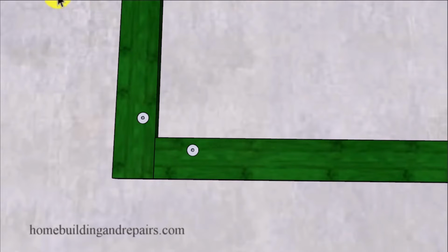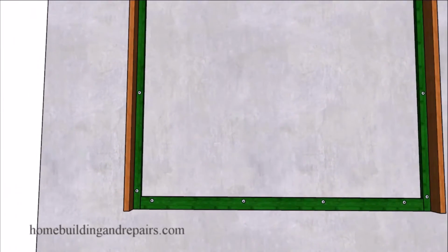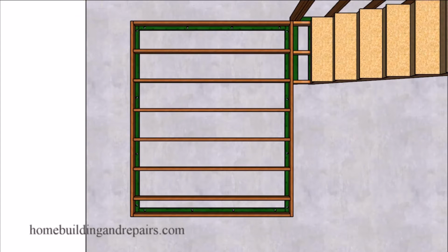And to give you a better idea of what I'm talking about, let's go ahead and install the rim joist on each side. And if for whatever reason you need to notch any of the framing components for the floor joist or the rim joist here, that's usually not going to be that big of a deal. But you can see here where all of the pins are located in an area where they are not going to be underneath any of the other joist or the rim joist.